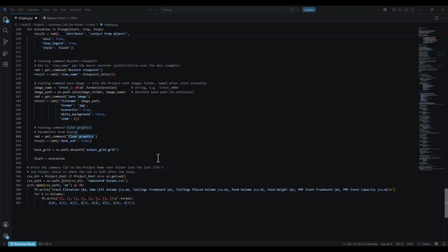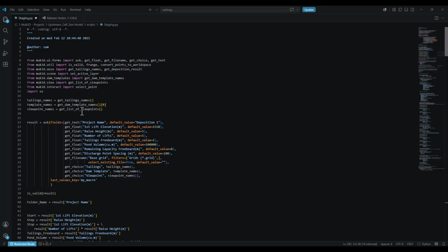Alright, I'm not saving this tailings layer, but I do kind of want to be able to set the increment on those tailings contours at the user interface level. So I'm going to add another float here that the user is going to pull in to the user interface, and that is going to dictate the tailings contour spacing later on. Now, once again, everything here is listed in meters. I know my project's in feet. Don't do this. Be consistent. But we are where we are now. There's no turning back.